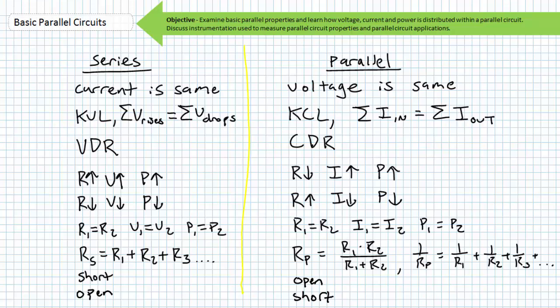And the only essential point I can add to this checklist is this bit of personal advice. Visualize circuits from the perspective of flowing current. If current has no choice but to flow through a single path, elements in that path are in series with one another. If current has a choice between paths, these paths are in parallel with one another.